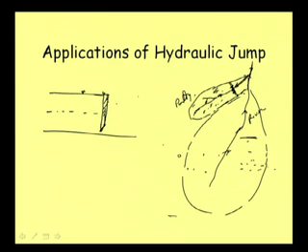But suppose we want to maintain the water at this much level, so some amount of water we need to release downstream. But say normally in this slope water is moving at a normal depth, but here when we are releasing it from a smaller depth, it will be moving with a high speed, and that may move as a supercritical flow.